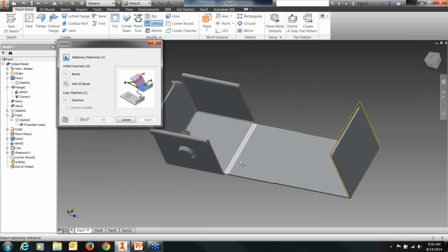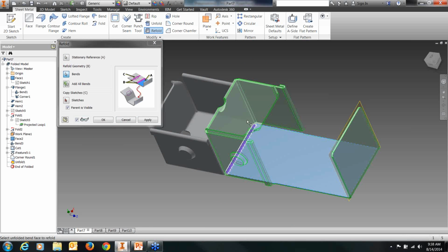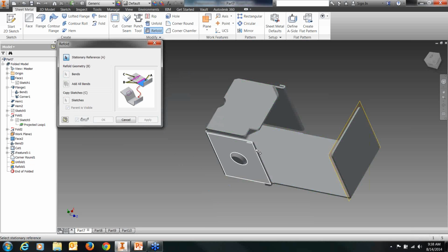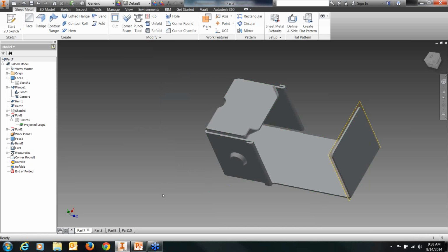I chose to unbend. And that is basically designed for if you wanted to make certain edits there, but you wanted just that portion as a flat surface, you can go through there and add your features. And then you can go back and say refold about that reference point, and it'll change it back to the particular fold method that it was at.